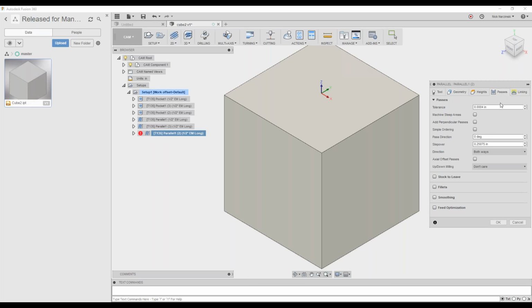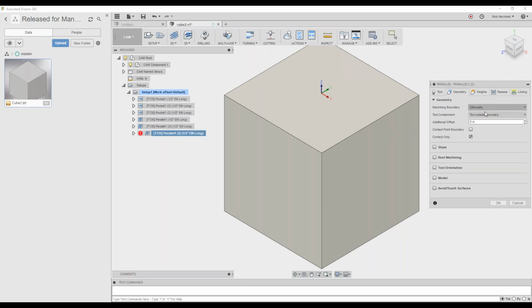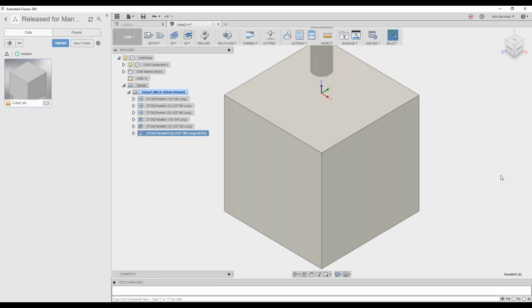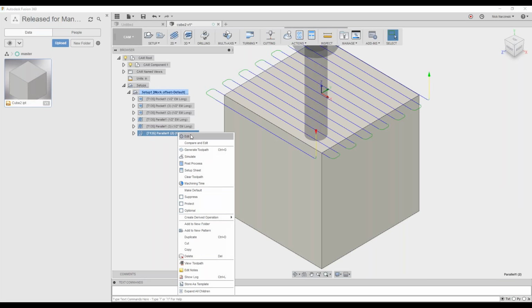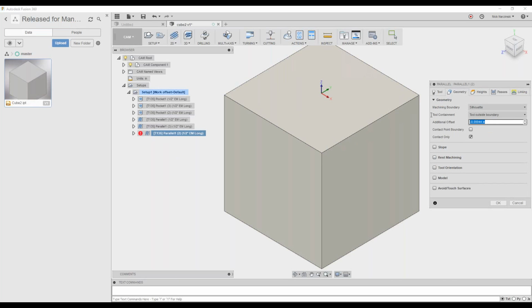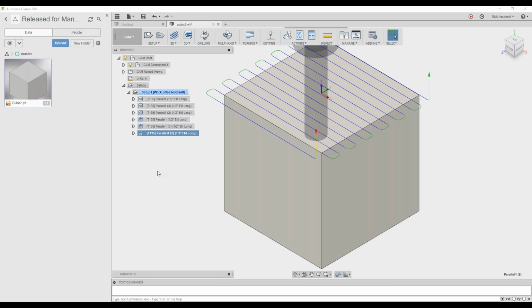And if I go back there and hold down the shift key and hover over that, you can see the parameter name for that is the word tolerance, all lowercase. So I'm going to reuse that. I'm going to say negative tolerance times 1.1. Hit enter. And that toolpath, so let me show what that calculated to. It calculated to negative 44,044. And when I highlight that, so now that toolpath no longer drags on the outside.